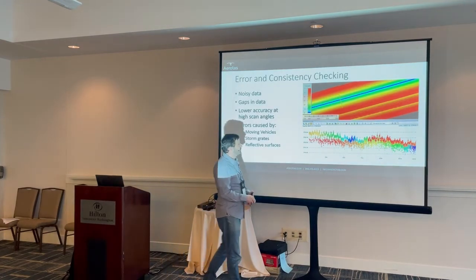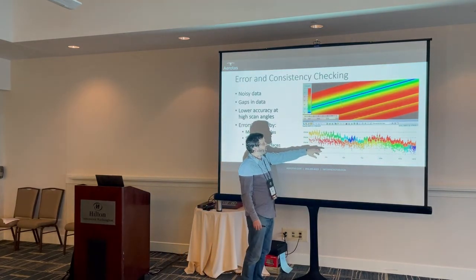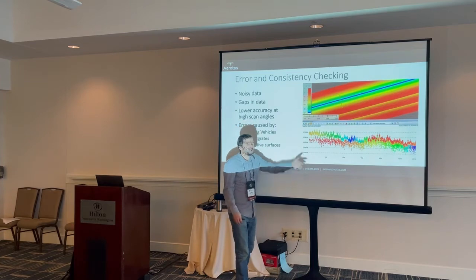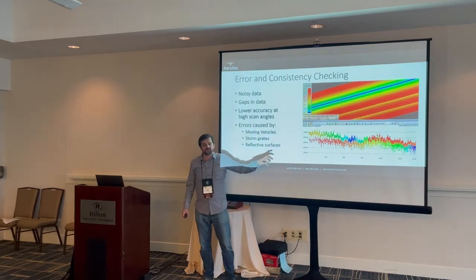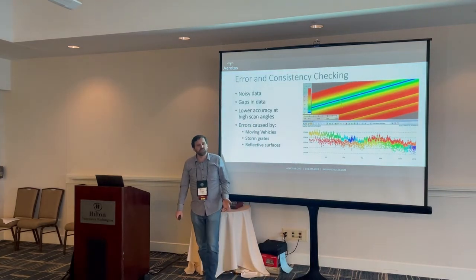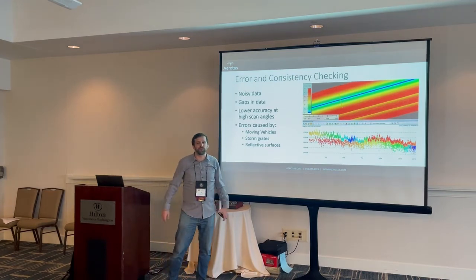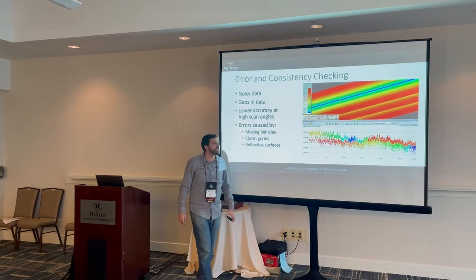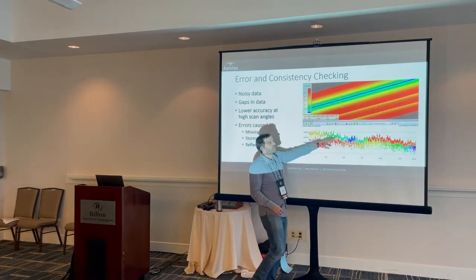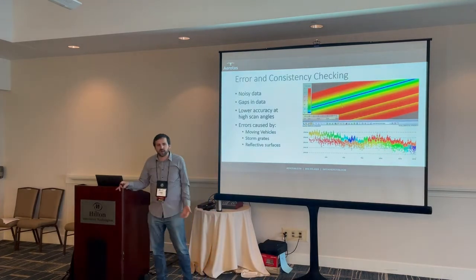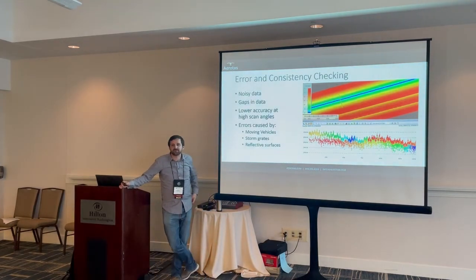And I should point out, these differences are fairly exaggerated. This was an example used because it was particularly bad. Really, even if you don't process this, if you don't fix for stuff like this, it'll be adding a couple tenths of a foot of error, but it's not like you're gonna be off by 2 or 3 feet or something like this. When it is taking the statistical average of all these points to create a surface, it's not gonna create crazy errors, but we care about getting that last 1 or 2 tenths of a foot of error.